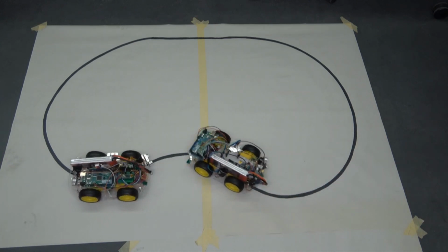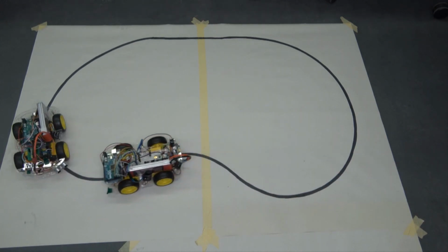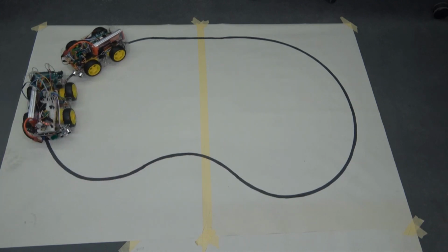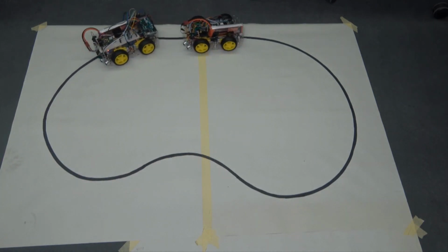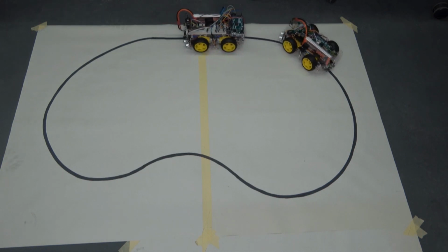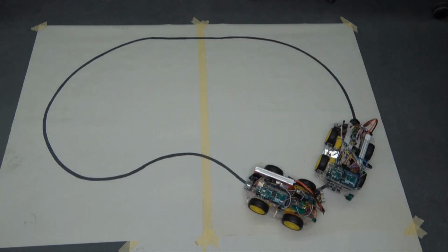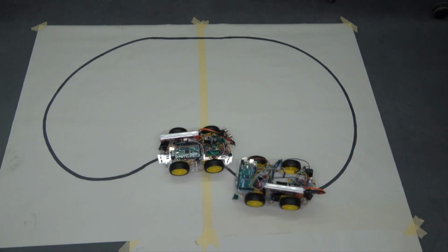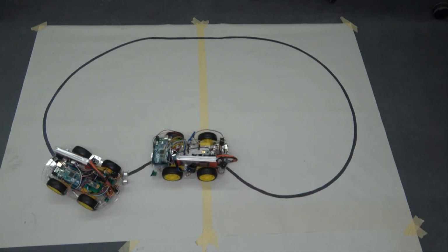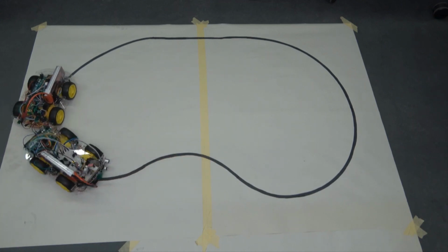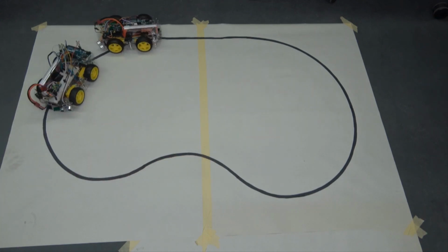Now we also monitored the MQTT server to see if the messages are exchanged correctly. And we could see that the robot cars connect to the message broker after they were turned on. And later on, we observed that the fast car sends an overtaking request after reaching the slow car, and then the slow car responded with a message accepting this overtaking request. And with this, we conclude that the envisioned application scenario was correctly executed with the generated code.